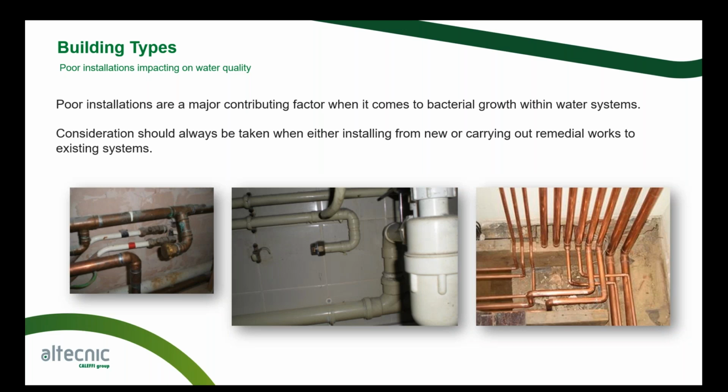You might have to rejig the pipework slightly, but it's still very important that we remove that issue with the dead leg. Again, the one in the centre could be easily resolved by changing this T-piece here for an elbow maybe. But again, we're creating more risk by leaving this dead leg here.